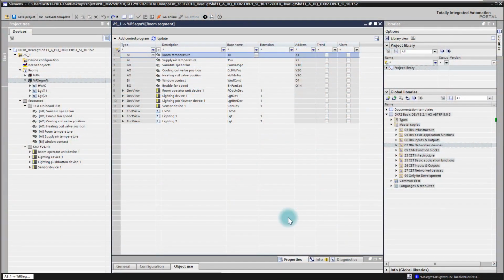In this video I'm going to show you how to change the push button assignment to a group. I will show it today in an example with two lighting groups. Here is lighting group number 1 with the extension number 1 and lighting group number 2 with the extension number 2. The same processes and rules as I explain here in that lighting application apply also to the blinds or shading application and the push buttons for these applications.